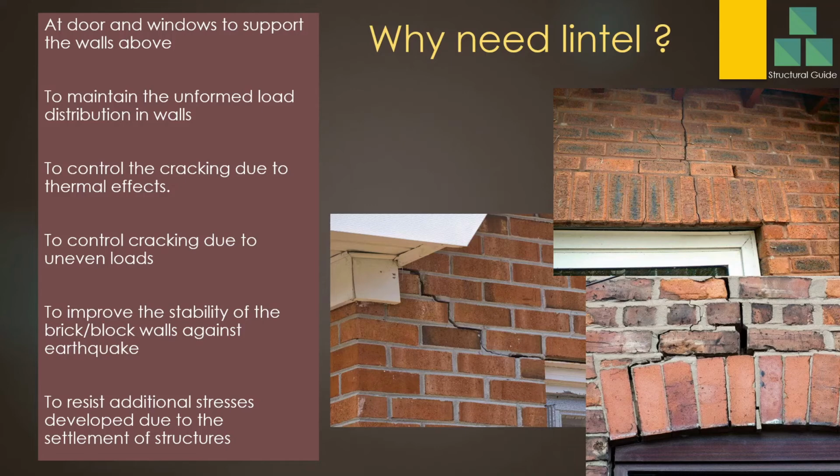Why do we need lintels? At doors and windows, to support the wall. I have discussed that already; you saw it in the last figure also. A lintel is used to support the brick wall above the door and window. If there is nothing to support the brick wall, there will be issues. You can see in this figure, here you don't have a lintel, so the cracks have propagated. Here you don't have a lintel, so a crack has developed. Here also you don't have a proper lintel, so the crack will propagate. Therefore, you need a lintel where you need to provide support.